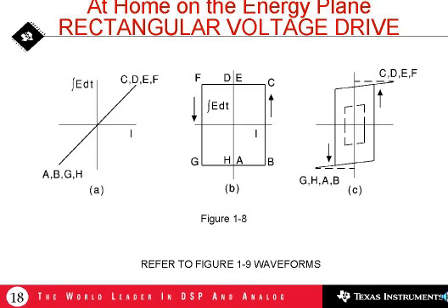So that characteristic must be at the 10 ampere point on the horizontal axis. And for the entire duration of that positive pulse, the current is fixed at 10 amperes. But the movement takes place along the vertical axis. If we start at point B, we will gradually move up toward point C. If this square wave happens to be, let's say, 50 kilohertz, that means the duration of the positive pulse is 10 microseconds, and the duration of the negative portion of the waveform is 10 microseconds.